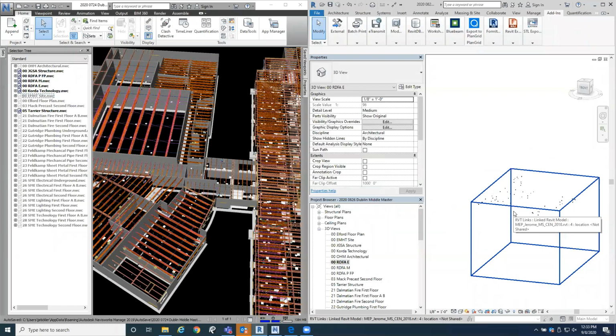For me, when I'm going through, I will actually walk the building virtually, and I'll be looking for ductwork or plumbing that's either lower than my ceilings, or maybe we have a drain line that's not in a chase.